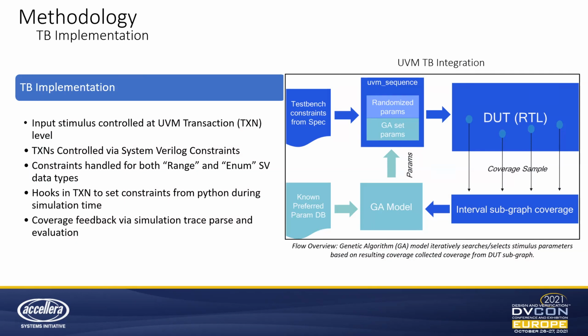So the approach discussed on the previous slide was applied to a UVM test bench using a standard SystemVerilog UVM framework and methodology. Starting in the UVM sequence, the sequence items were parameterized using SystemVerilog constraints. So this provided a way to direct random sequences by overriding these constraints. And this is building on top of our random constraint. This approach, I guess, has the benefit of being simple and quite generic, and allows us to target a wide range of test benches and contexts.